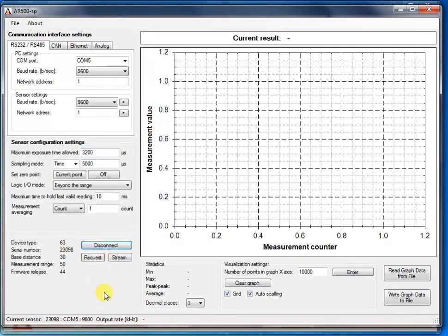You can also use the device manager to go and verify what COM port to use. In our case, we had COM5 9600 baud, and as you can see, once I connected it, the grayscaled areas will light up. And let's just go through it real quick.